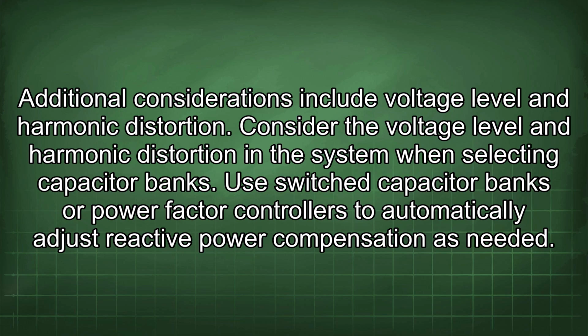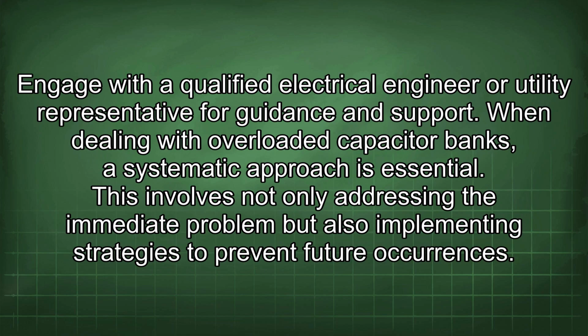Use switched capacitor banks or power factor controllers to automatically adjust reactive power compensation as needed. Engage with a qualified electrical engineer or utility representative for guidance and support. When dealing with overloaded capacitor banks, a systematic approach is essential. This involves not only addressing the immediate problem, but also implementing strategies to prevent future occurrences.